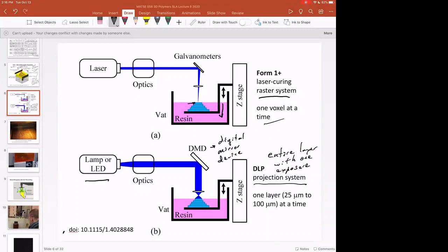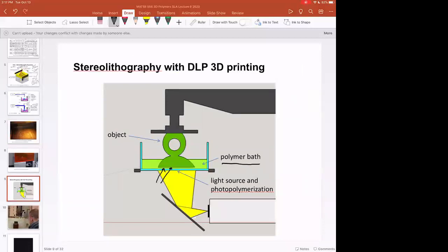Now, what's interesting about these photopolymerized layers is that they're a little soft. And so even in this, we say that the polymerization is going to be between two hard objects, but companies like Carbon leverage what they call the dead zone at the window. So their gap is not necessarily the gap between the part and the window, it's the gap between the part and the dead zone. And at the edge of the light, the part is a little bit soft. So you have 5 or 10 microns of wiggle room.